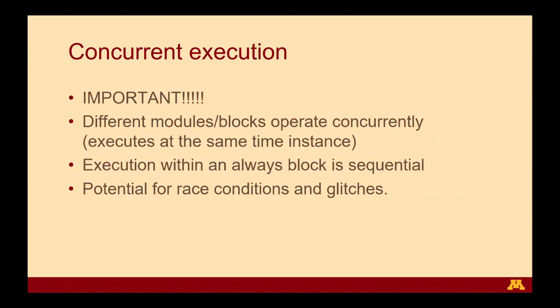One important aspect for those of you especially who have not used Verilog before and are new to hardware design languages in general: Verilog is entirely concurrent execution. Traditionally, when you look at C code or software programming, you think of code as a set of statements which are executed in sequence.